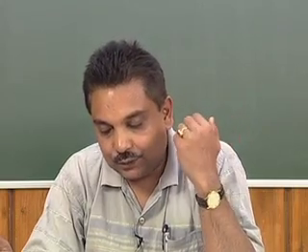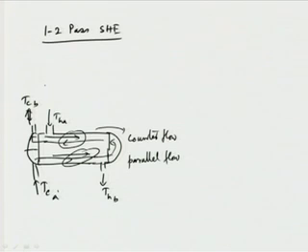So, that is very important to decide where we should put the tube side. Should we put the cold fluid entry here and output here, or entry there and output that side? That is very important. We need to maximize the driving force for the heat exchange.